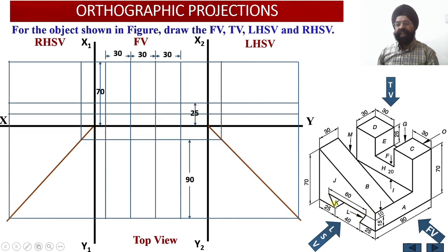After you draw this, the next thing is, please check, there is an internal slot over here. This internal slot will be required to secure the solid onto the base of any given slide. Now this is an angular slot. So the height of this lower portion of the slot is equal to 15 millimeter. So I will be able to see a dotted line over here at a height of 15 millimeter from the base.